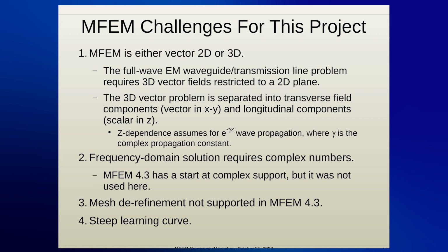Mathematically, the 3D vector can be separated into a transverse field and a longitudinal field. And so one's in vector and one's in scalar. So the key then is just to get those into finite element spaces so that it can solve, and I'll cover that on the next slide. The other issue I had is that frequency domain solutions require complex numbers. And when I started development, we were at MFEM 4.3, and I haven't moved off that yet. But MFEM has a start at complex support, but I didn't use it in this work.